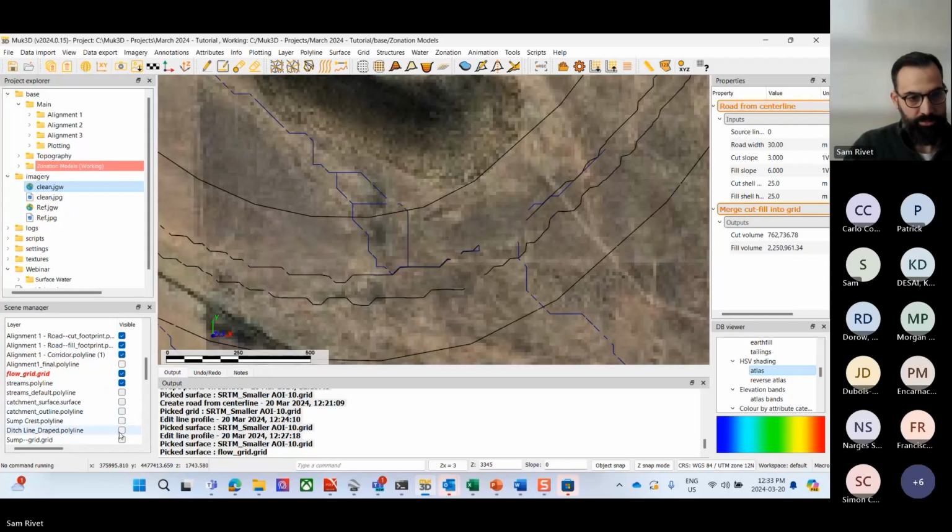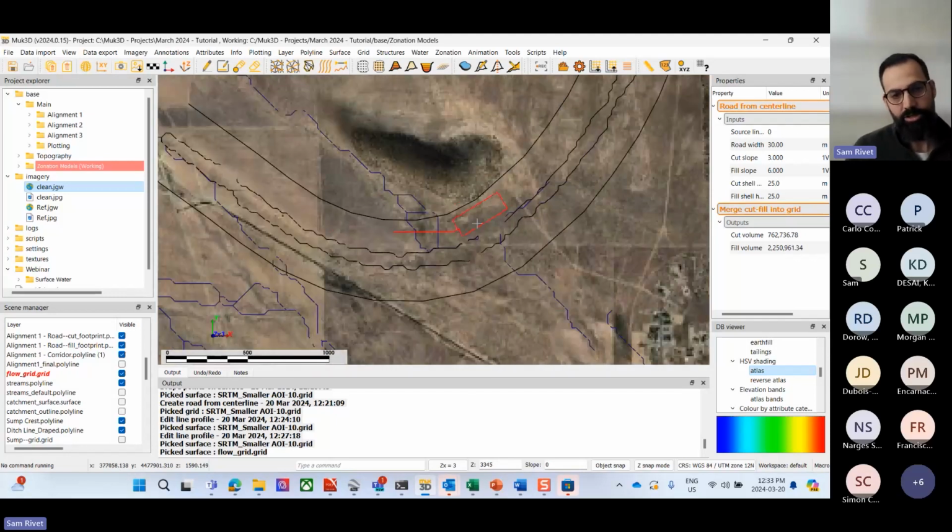So just something that looks like this. There's my ditch, and I'm going to run it to an excavated sump, or excavated hole, that I'm going to place within my right-of-way. But I need to know how to size this storage area. How much water should I expect?